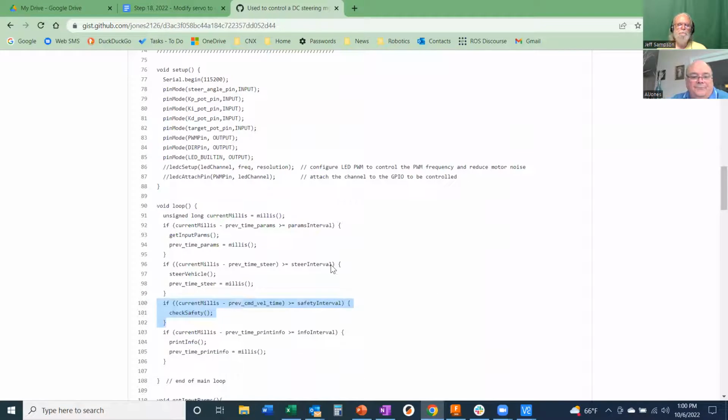Well, it sounds like you've got some more to play with now. Yeah, I thought I had my PID settings and I don't. And yes, there's no sense to tune it to something that's not going to work. So try to get the fundamental thing to move back and forth before you start playing with the PID settings. I think you thought you had that to start with, but I don't think that's what you wanted.